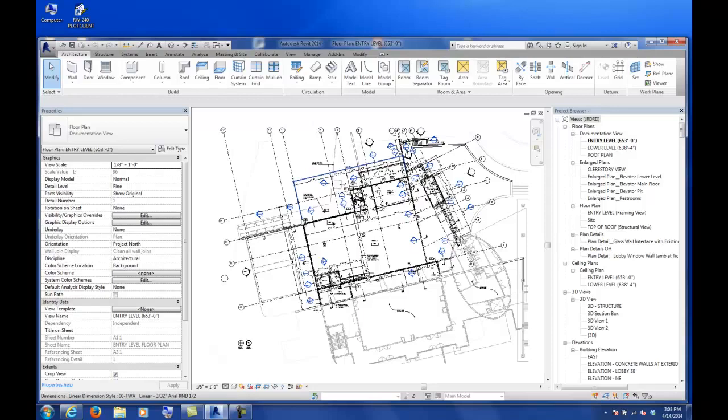When it's detached, so you take your laptop home and do some work, Revit is going to give you a warning when you open it because it can't find the central model, and it'll basically say do this at your own risk. Because if something else changes on the central model before you sync back, it might not allow you to sync anymore.